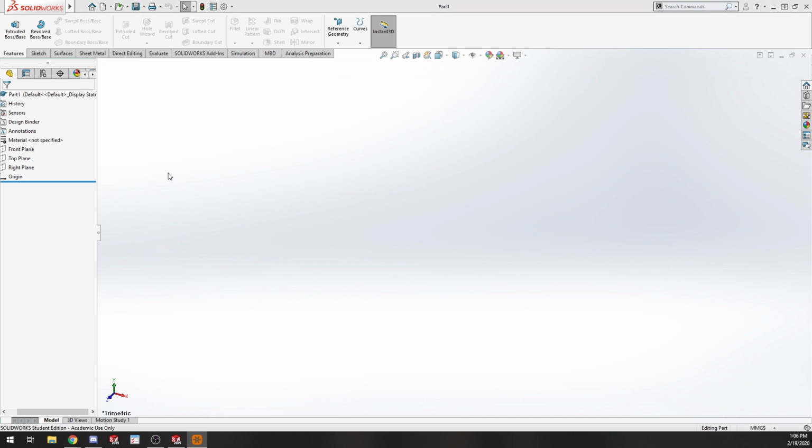And with a boundary, you can have a bunch of different profiles in between. It's just like a loft, except you have way more control over each profile, and you can define constraints on any profile. You also have control of your curvature, with those guide curves we were talking about, as well as on all the profiles that you're trying to go in between. So you have a lot of different options there. Boundary is basically the more powerful version of loft.